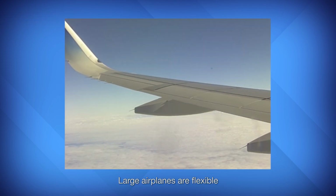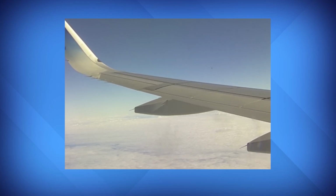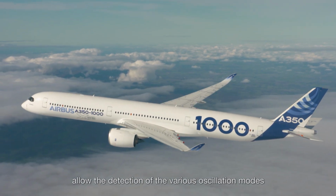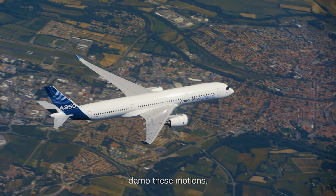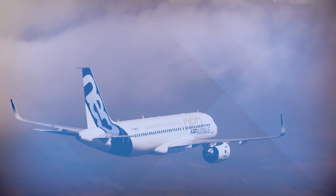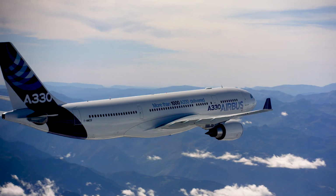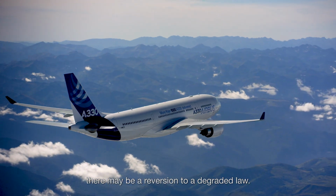Large airplanes are flexible and there may be comfort issues in turbulence. On fly-by-wire aircraft, the available sensors allow the detection of the various oscillation modes on all axes, and specific control laws damp these motions, at least partially. In case of failure of at least 2 computers or 2 identical sensors, and sometimes more, there may be a reversion to a degraded law.